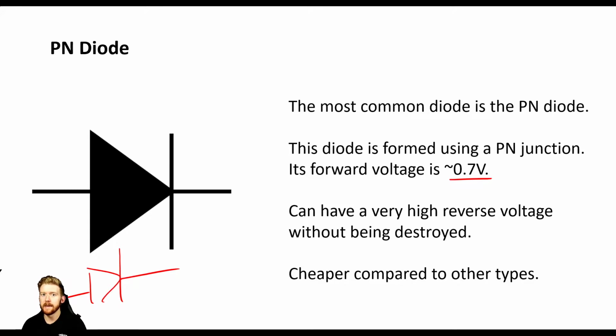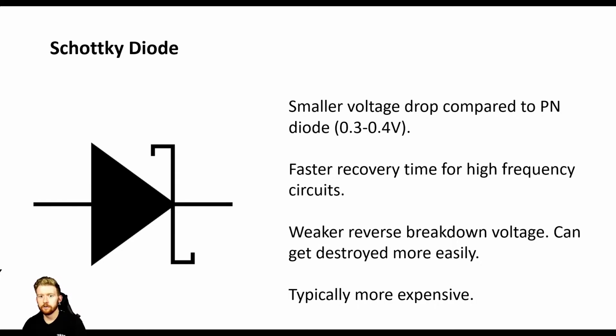So a PN diode is a pretty good, robust diode for withstanding those voltages. That's not to say that every PN diode is built the same and can all withstand the same reverse voltage, but that they are generally stronger compared to some other types of diodes. So PN diodes are good for general purpose uses if you need a little bit higher reverse voltage breakdown limit.